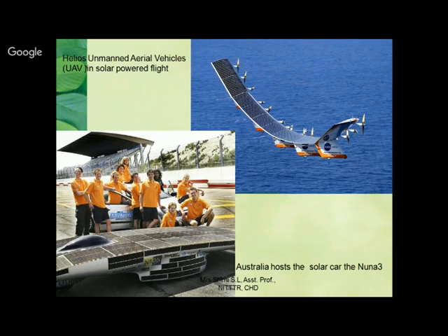So that power which you have generated, you can give it to the grid during the peak hours. And in the evening when you feel, okay, I want so much power to go back home also, by that time, nowadays everything is programmable. You can set that when the battery is drained more than this amount, please stop giving to the grid and charge your battery fully. Such mechanisms can be done, and this can be done in our institutes itself.